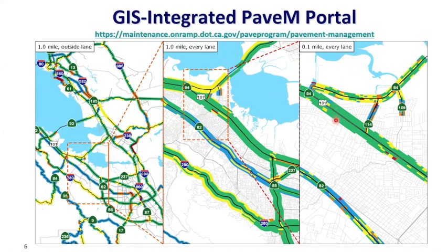Okay, they are only the rightmost lane-based or the worst lane-based. But California is at the tenth-mile level, that's a MAP-21 requirement. And for every single lane, we have the information. And all these little segments out there, it's about a tenth of a mile. Okay, so that's the level of detail this pavement management system is all about. It's a lane-based management system.